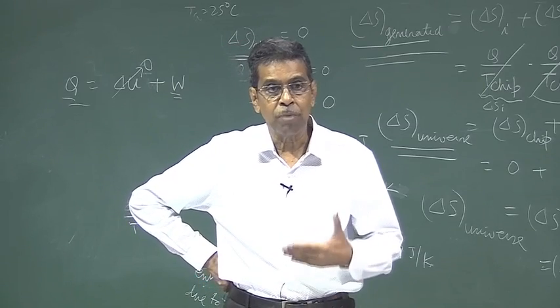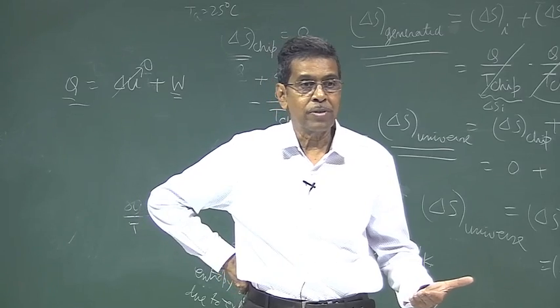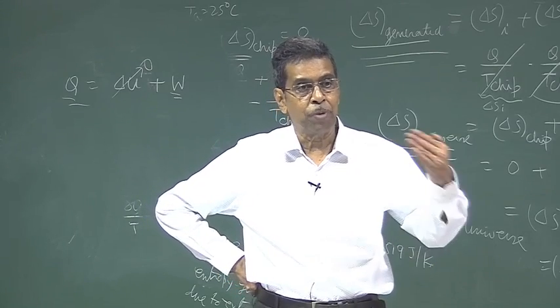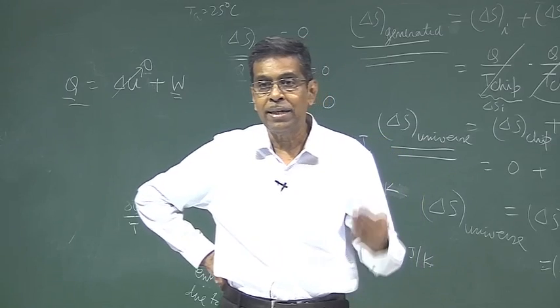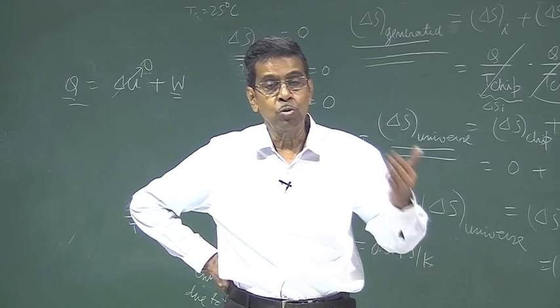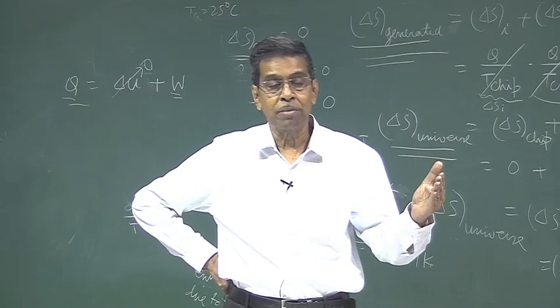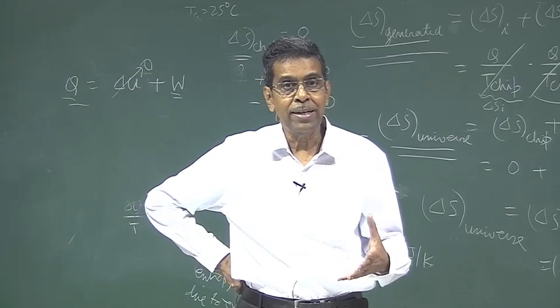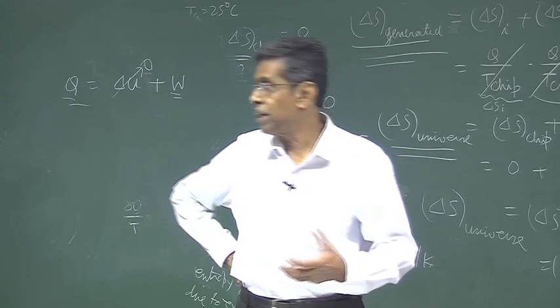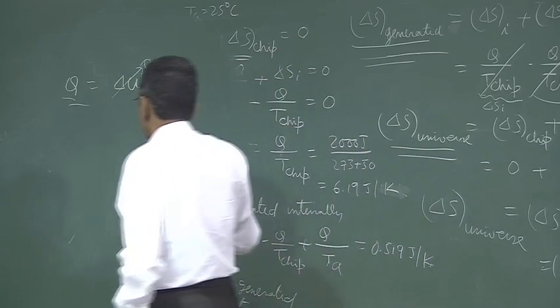And then from that, we had the concept of entropy, which is defined in terms of its change. The entropy change in a process is given by the integral of delta Q by T if the two states are connected by a reversible process. That means it is defined as the integral of delta Q by T in a reversible process.